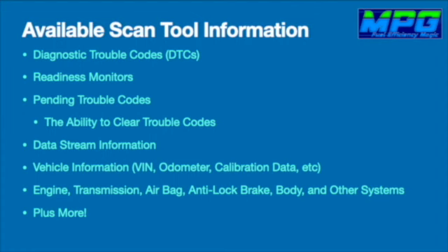Now, the scan tool is going to give you diagnostic trouble codes, and be able to clear them. Pending codes, be able to check the readiness monitors, data stream information, vehicle information like the VIN, the odometer reading, calibration data, all kinds of stuff like that. Plus, it's able to tie into not just the engine controller, but transmission controller, airbag module, anti-lock braking module, body control module, and a whole lot more. You can roll the windows up and down with a good scan tool.